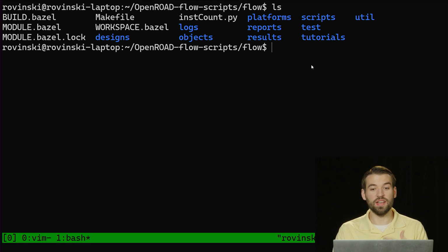Unfortunately, Python is not quite as well supported as Tcl is, so we can't access it through the GUI at this moment, but we can at least still create Python scripts and then use OpenRoad to execute those. OpenRoad has both an integrated Python shell and Tcl shell, which is the primary way to run this. You should run the OpenRoad executable and use the shell there rather than trying to run a Python shell and then import OpenRoad. That may exist in the future, but at least right now the best support is to run OpenRoad first and then use that shell.